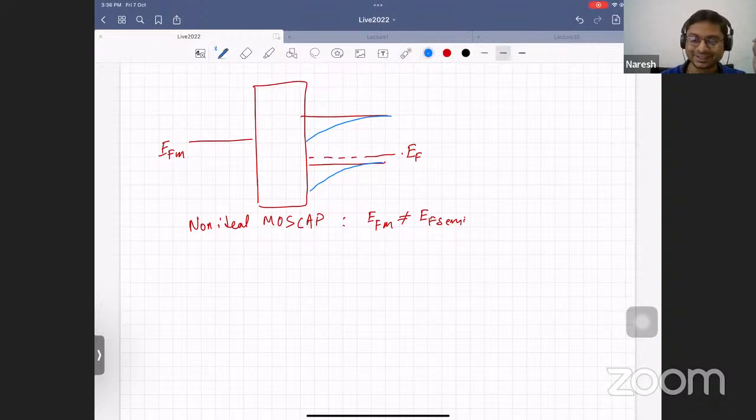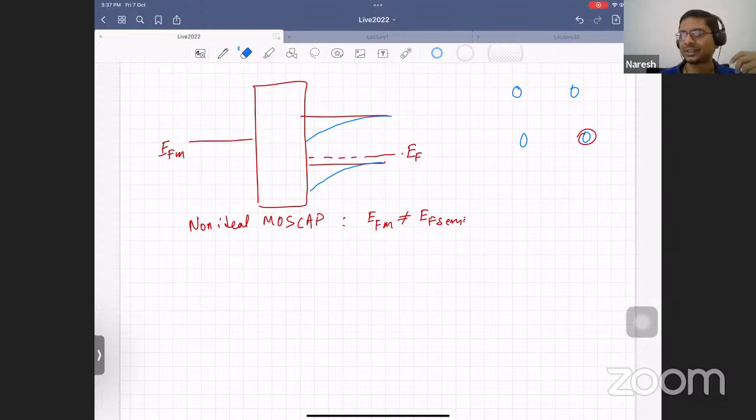Let's say you have silicon, silicon, silicon, silicon. I'll change the letters. There are silicon atoms like this, right? How do you know that you're going to replace one of these with phosphorus? Why can't phosphorus be here? It turns out you don't have to do anything much. If you diffuse, it will automatically go into this region because that's where the energy will be minimized overall.